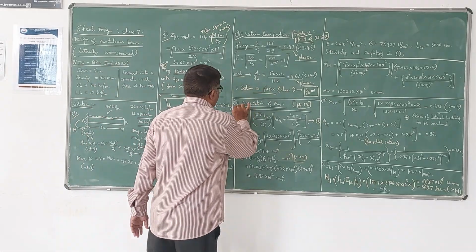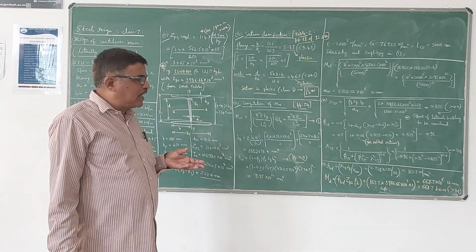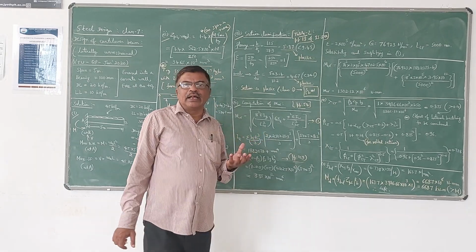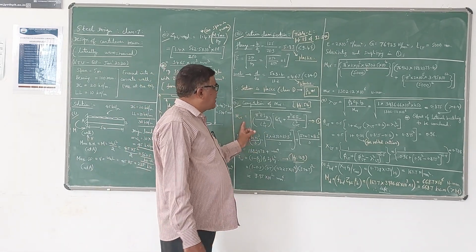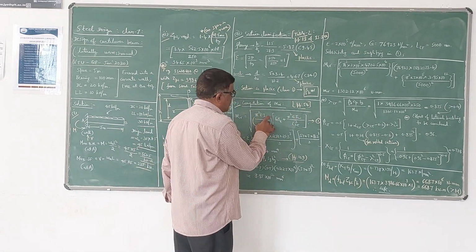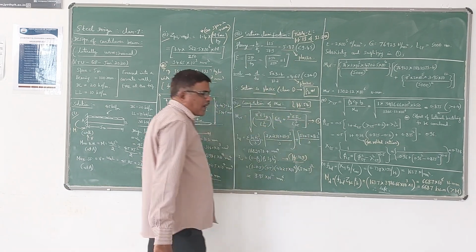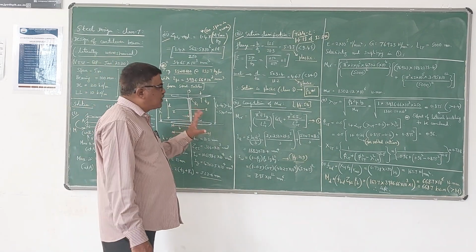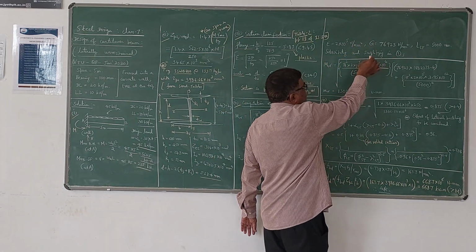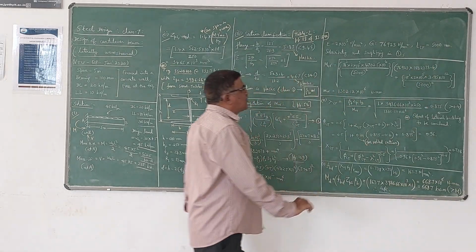So it is okay. Now the third step is computation of the Mcr value, which is the elastic critical lateral buckling moment in the case of laterally unrestrained beams. This is given by the formula on page 54. Mcr is equal to the root of pi square E Iy by LLT square into G It plus pi square E Iw by LLT square. If you substitute the values, E as 2 into 10 power 5 Newton per millimeter square for steel, G as 76,923 Newton per millimeter square, and LLT as 5,000 mm.